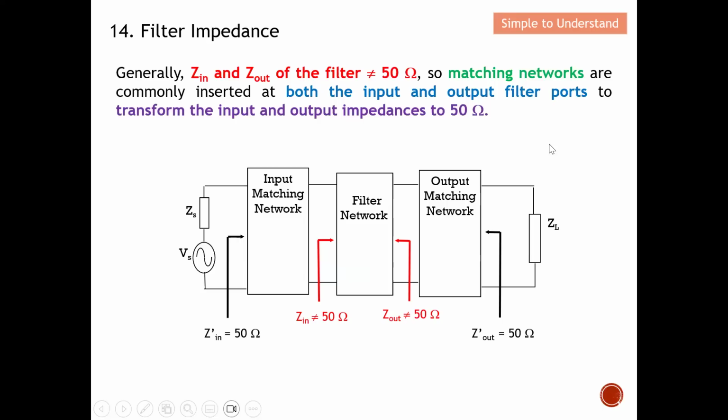If you have the design of an amplifier, you can go through the filter network, but we need to ensure that the impedances are matched. But if not, let's say I'm going to sell this filter design, I need to ensure that when we look into here, it must be 50 ohm. So therefore, this is on the filter impedance.